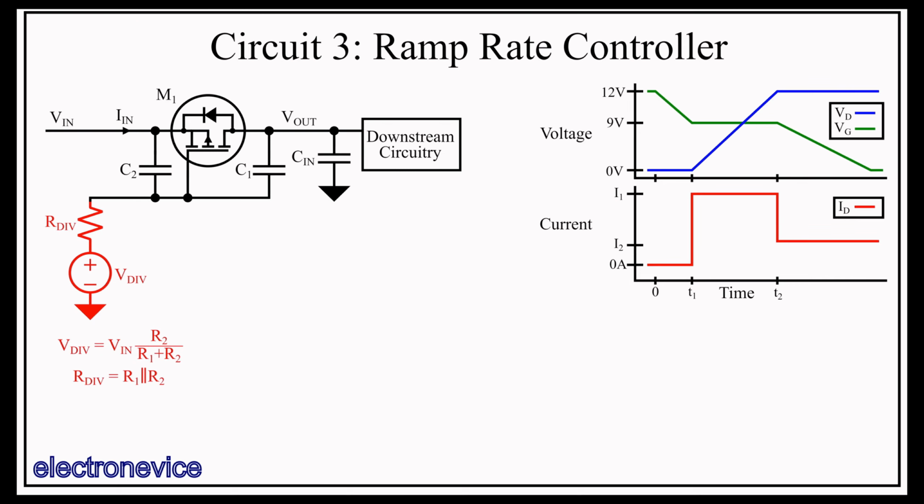Second, it impacts the charging circuit by setting the charging voltage. But most importantly, it allows a direct, easy-to-see discharge path between gate and source that ensures that the circuit will reset when the power is cut to the circuit. So now that we have this Thevenin equivalent circuit constructed, let's treat this circuit a little differently and actually do a little design for our inrush application with a few requirements.